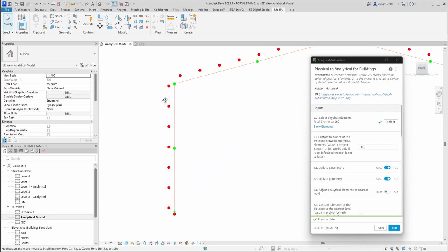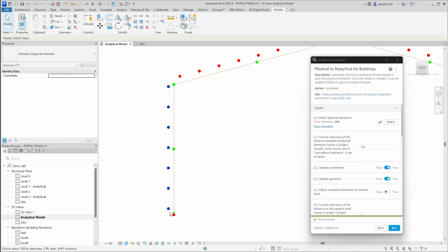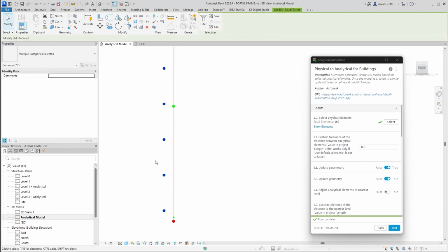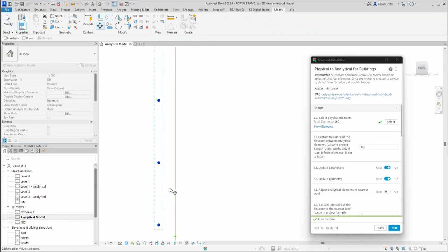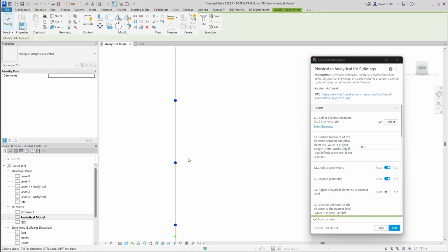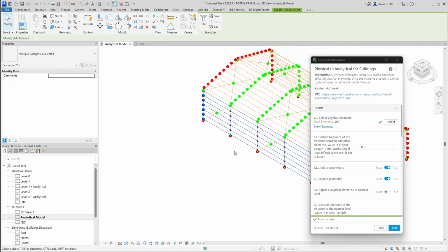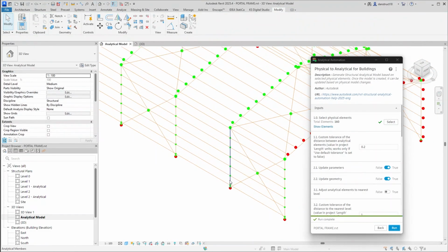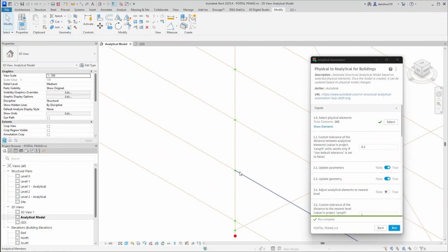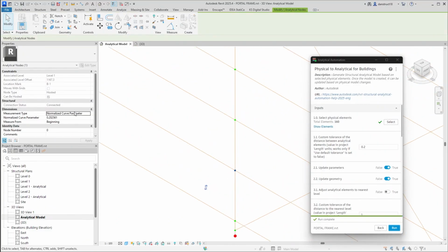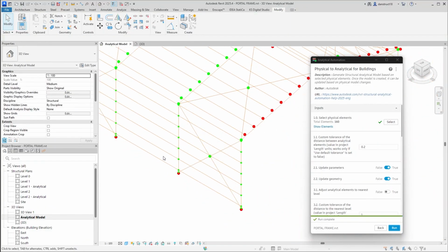What I'll do is that I'll go over here and make a selection over my girts elements. There we go. And I'll go ahead and use the move tool. So I'll click on move. I'll make a selection from any of the endpoints and then move them to fall on my column. Once I've done that, I want to switch to any of the views to make sure that they are properly connected to the columns, as you can see. So just make sure that they are connected as such.